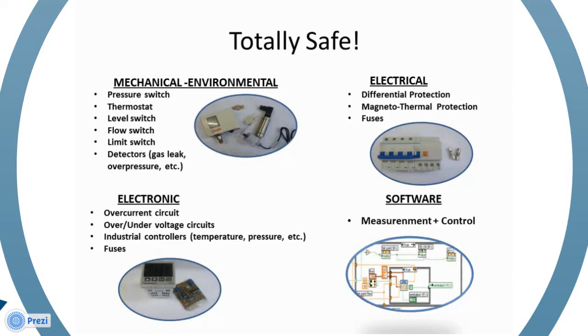How does it work? The pressure sensor is regulated for working in a particular range, sending proper millivolts or milliamps to the electronic interface. So if this amount exceeds the electronic system in the interface, it cuts off. But suppose that the mechanical safety device fails and the electronic safety device fails, or the student cuts it out. In this case, the software device operates as the software package has designed it for working only inside a particular pressure range.